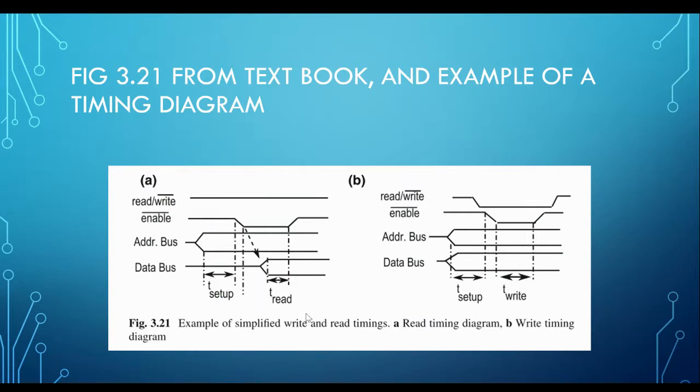All this has to do with the protocol. That's why serial communication has very minimal protocol. SPI and I2C have more protocol, but they can do more complex stuff, like communicate with multiple devices. This is something that normal serial RS-232 cannot do, right?